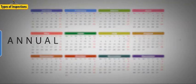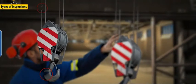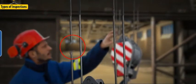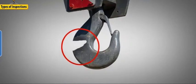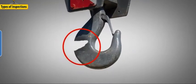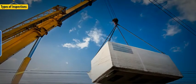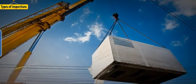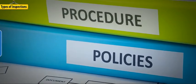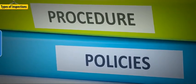Pre-shift inspections and maintenance inspections are two types of frequent inspections. Pre-shift inspections spot obvious problems with the crane before a load is ever lifted. Maintenance inspections are generally performed weekly or after critical lifts that are close to the crane's capacity. Your company should have procedures in place for all inspections, including checklists and documentation procedures.